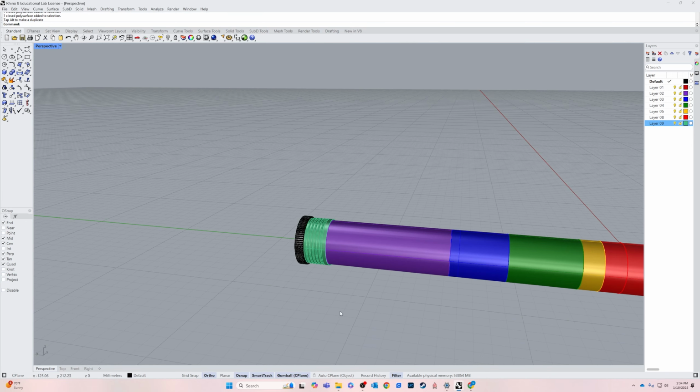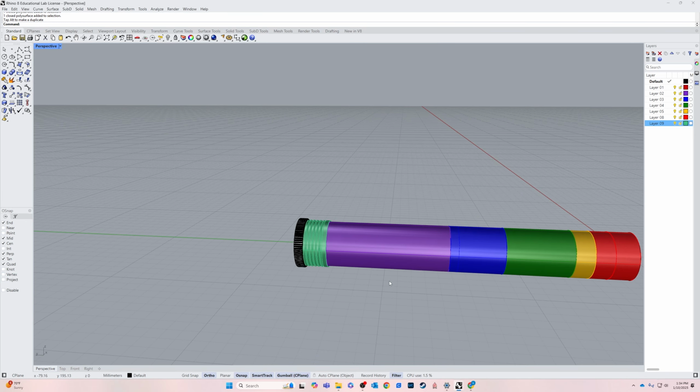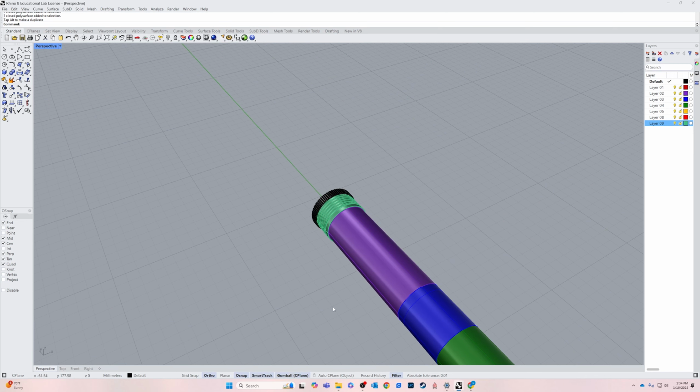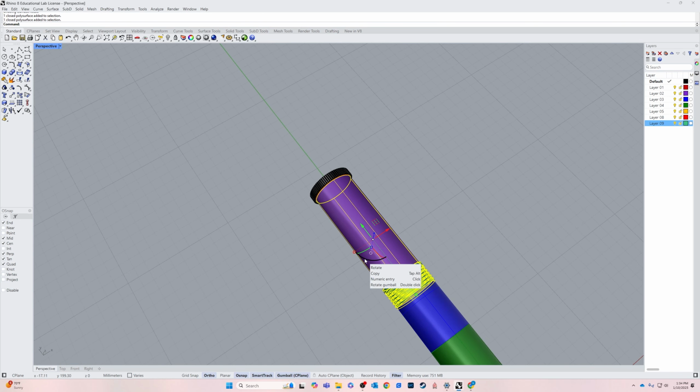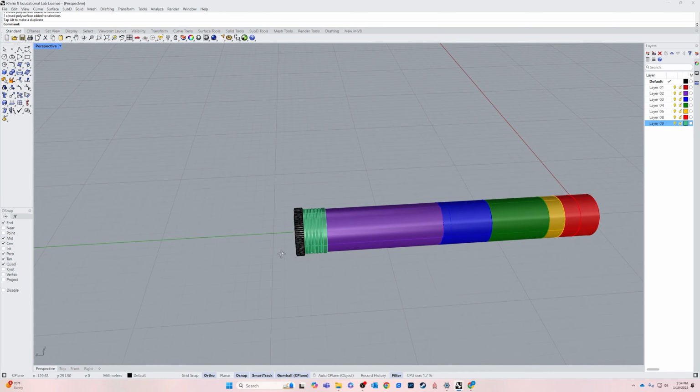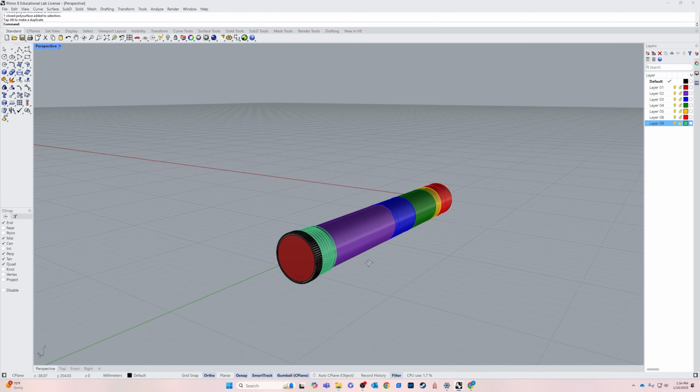Yeah, because I had my object snaps turned on, my ortho turned on. So it snapped it into position. So again, I have it like this. If I select this and shift select to add to the selection and then grab the blue rotate here and just rotate it twice with ortho turned on, it goes all the way back over there.